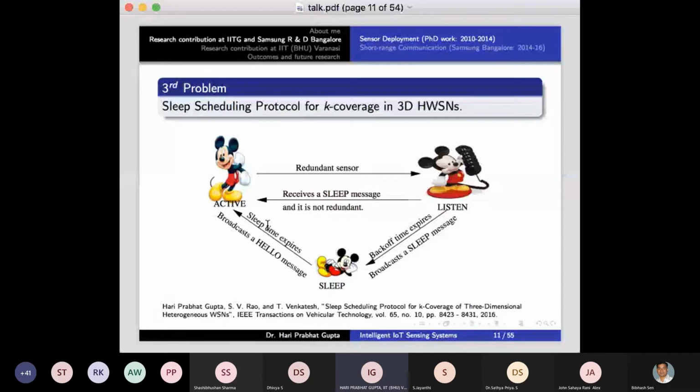In the random deployment, we can randomly deploy with the help of some probability or statistics, for example, a Gaussian distribution like this one. Now, both approaches have advantages and disadvantages. In the random deployment, the advantage is that very little effort is needed while deploying the sensors. We just scatter the sensors, so we are not worried about the position. But in the deterministic deployment, the position is important.